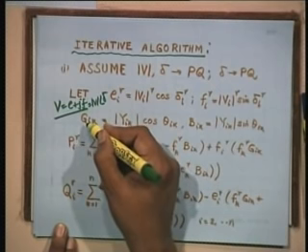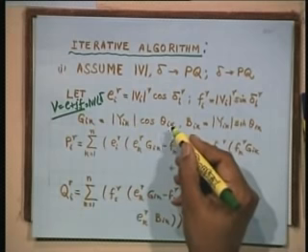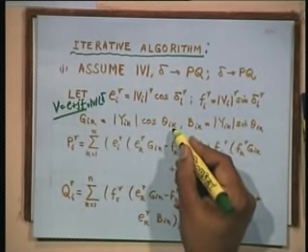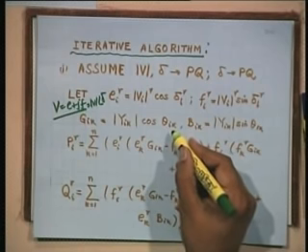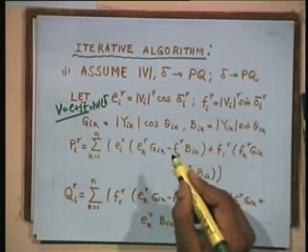Gik, the conductance, the real part of Y bus, is Yik cosine theta ik. Please remember, theta ik is close to 90 degrees because the resistance is very small. In any well behaved power system, in any normal power system, R by X ratio is ought to be very small. X is roughly 10 times.